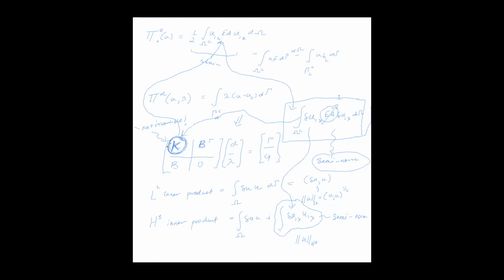In other words, maybe we call this big matrix A. You have to solve it by inverting big A, the whole thing. Whereas most of the time with these kinds of systems, you're going to want to segregate them, and those segregated methods often require the inverse of K. So the formulation I've given you so far, where you have the strain energy but no strong boundary conditions, with the boundary conditions enforced through a Lagrange multiplier, is going to lead to a stiffness that's singular.